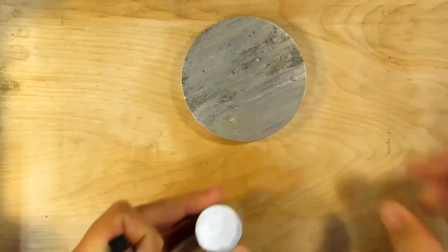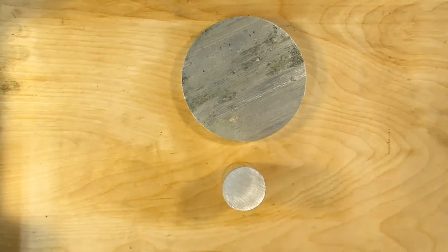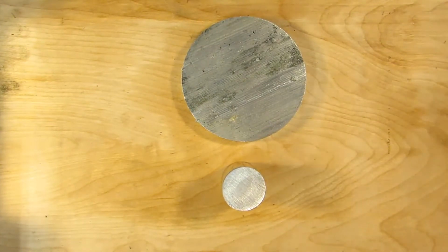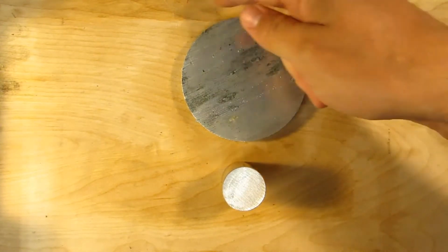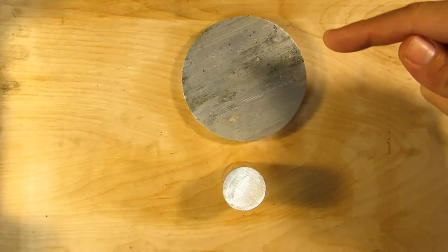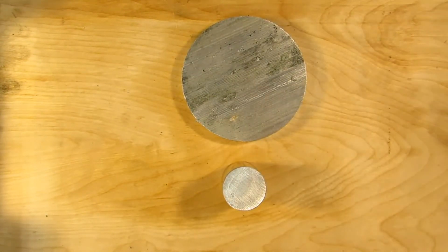So I've got two pieces of aluminum here. One of them is larger than the other one. And when we talk about RPM, the critical thing in figuring out what your RPM should be is what is called surface feet per minute, and that is your cutting speed. On the lathe, it would be how many feet of circumference of the material is moving past your cutter in 1 minute, or on the mill, how many feet of cutter is moving